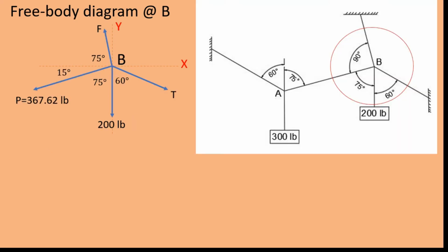So at point B naman tayo, free body diagram at point B. So yung nakabilog ng red dun sa drawing, yun yung kinuha natin. We have to cut the rope and then ma-expose yung mga forces na yan. So we have 200 pound na going downward. And then yung force P, tension yan. That's why lahat yan puro pahatak since that is tension.